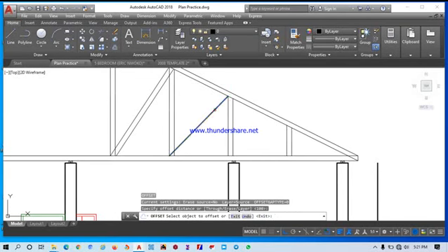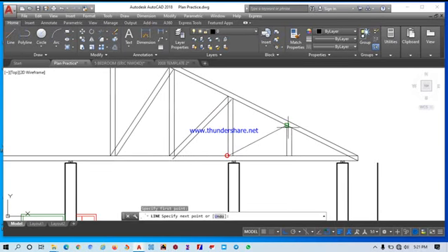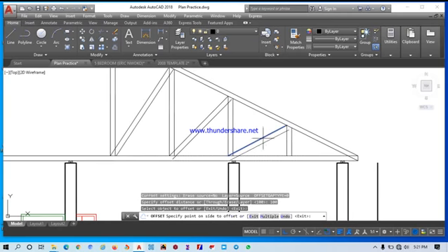You go to this place and you do the same thing also, until you have a limited space whereby your line can no longer be offset, then you can drop it right there. Alright, here we are. We're moving on. So I'll trim off and extend the necessary lines. While using your trim, click on shift to change it to extend.